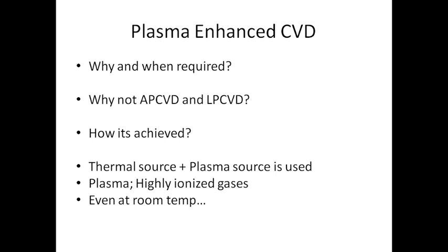So usually we know that the depositions will happen, there are n number of depositions that have to happen. Assume that we have already deposited one material and we want to deposit another material which requires a larger temperature. Assume you have aluminum deposited, and after deposition of aluminum, suppose you want to deposit silicon or silicon dioxide. You cannot put that wafer into the furnace, because if you put it into the furnace, the temperature goes to maybe around 1800 degrees centigrade.